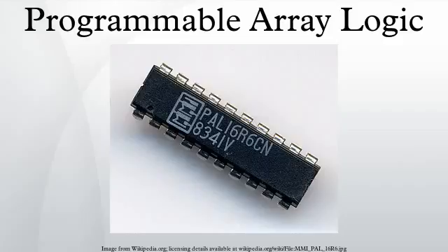These devices extended the PAL architecture by including multiple logic planes and/or burying logic macrocells within the logic plane. The term complex programmable logic device was introduced to differentiate these devices from their PAL and GAL predecessors, which were then sometimes referred to as simple programmable logic devices, or SPLDs. Another large programmable logic device is the Field Programmable Gate Array, or FPGA. These are devices currently made by Altera and Xilinx.